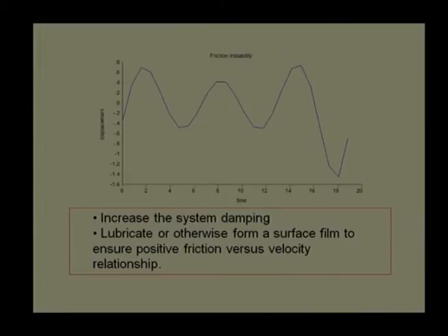Many times we are not able to give lubricant to machines related to textile operation, because we know the textiles will get affected by lubricant and it should be avoided. However, if it is possible to lubricate the surface, then it is always preferable to go ahead with lubrication and ensure that the difference between the static coefficient of friction and the kinetic coefficient of friction is decreased.